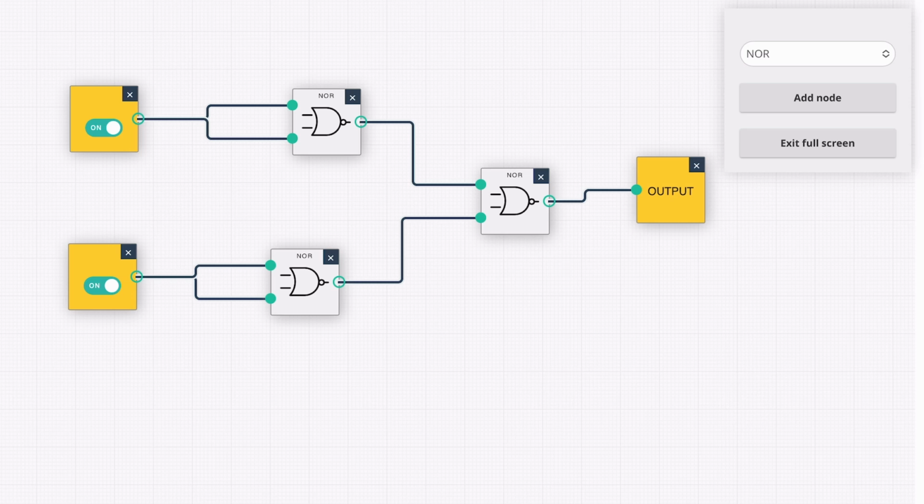Now we've seen that the NAND and NOR can be used to replicate all the fundamental gates, and what is even cooler now is that if we're able to show that any set of gates is able to replicate the NOR or the NAND gate, it is enough to tell us that it can create any gate. So any gate that you can create using the fundamental gates AND, OR, and NOT can be made using a gate or several gates that can replicate the NOR or the NAND. And this is very useful. You can use this to look at any gate system or look at any set of gates and tell whether they're sufficient to create all systems.